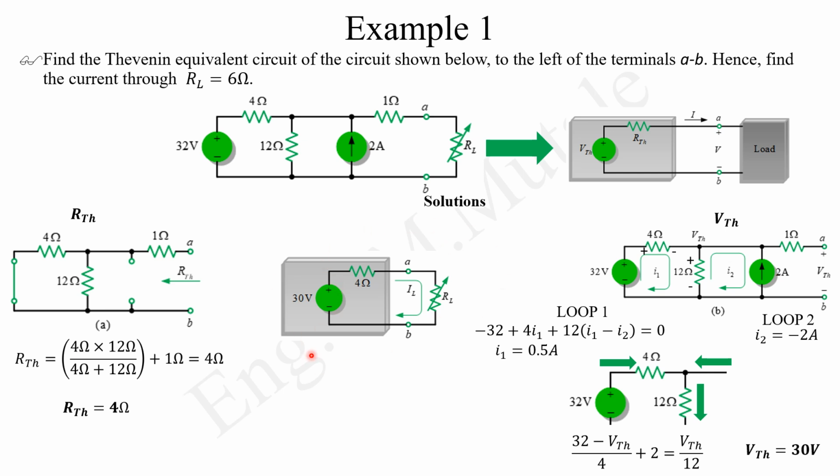And then now the question was saying, hence find the current through the load. So the current there, you can use 2 methods. If you want, you can use voltage divider rule. You've got this supply voltage dividing between this resistor and that resistor there. So when you do a voltage divider rule, once you have the voltage going there, you have the voltage and the resistance there. It will be very easy to find the current.